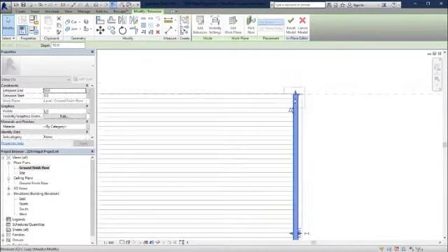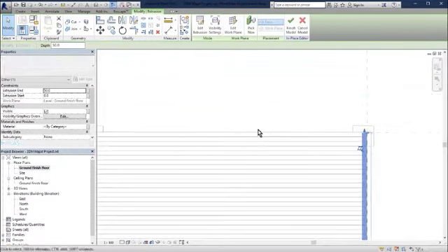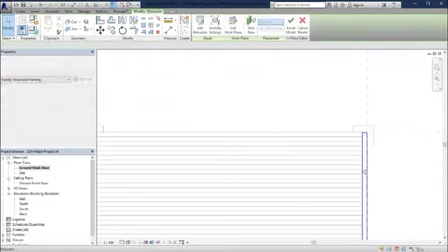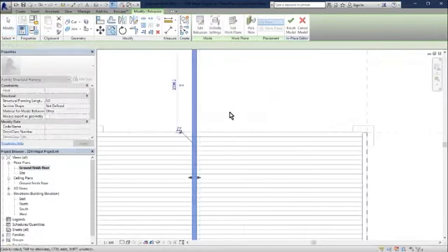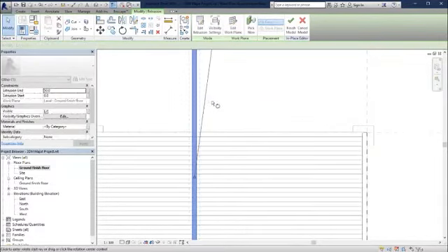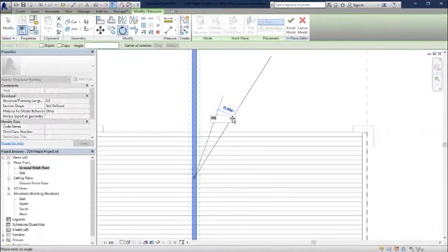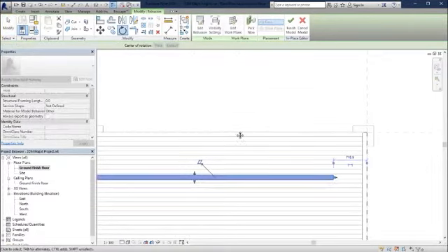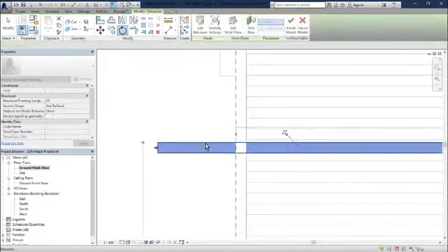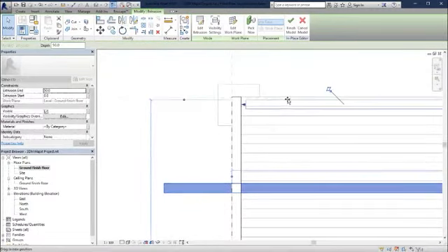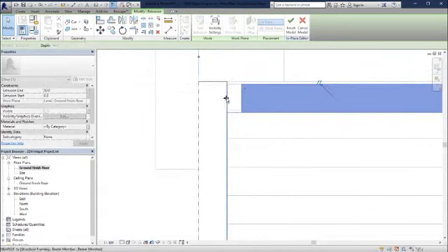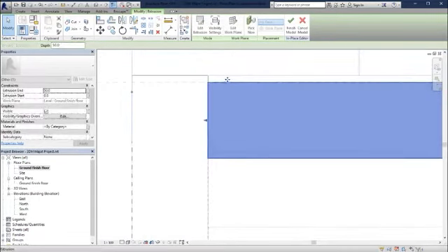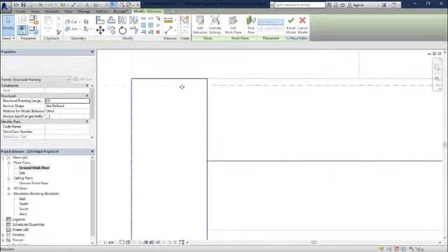That's where we were, right? And then we're going to copy this again. So we're going to click on it, CO, copy, and let us rotate that. RO is the shortcut to rotate, and 90 degrees. There we go. And we're going to move this in place here. And we are going to align here. Let's move this. Actually, that's where we should move it.